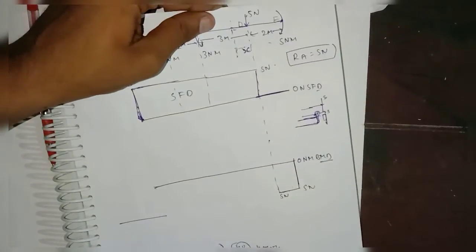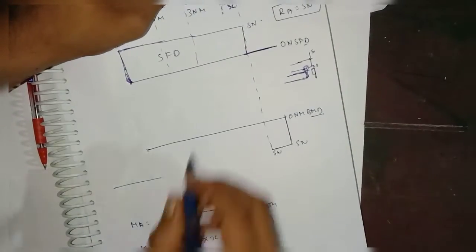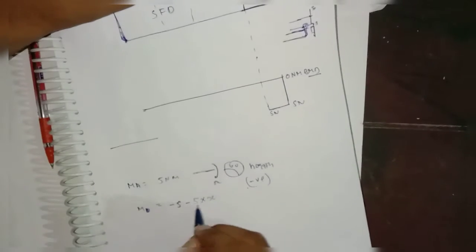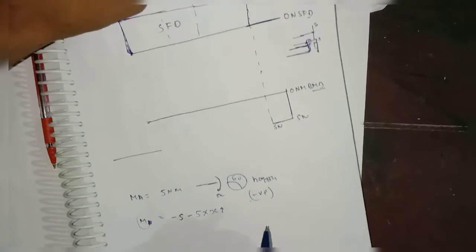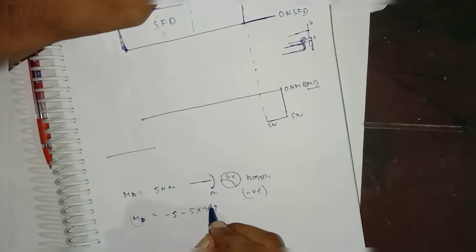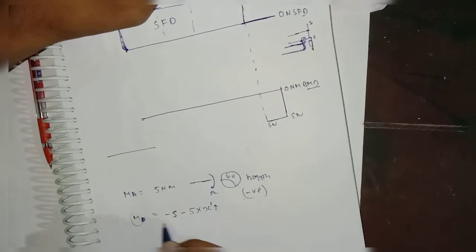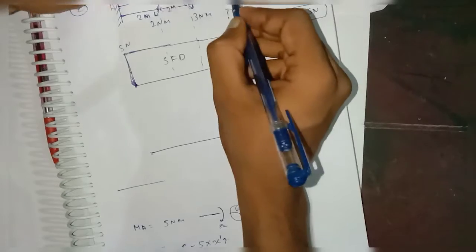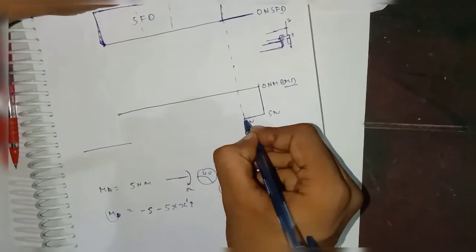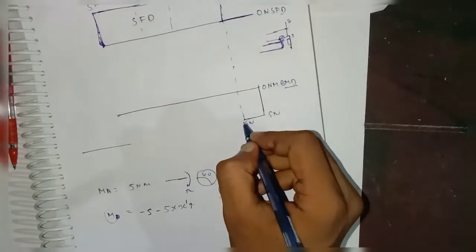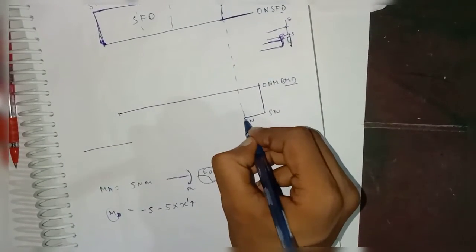So now this moment depends upon x, right? If you are increasing your x, then the moment will increase. Okay, and this also shows it will be a straight line only. Okay, so I am increasing x, right? So one thing also we are sure, from here we have to draw, our moment is increasing linearly after this point.